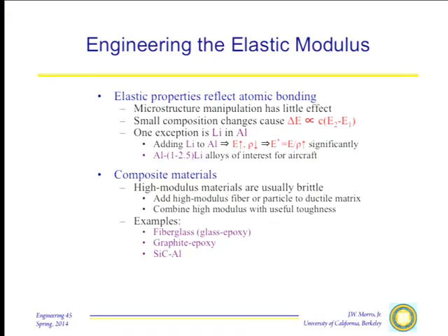You've got a problem because the limitations on the car will be the performance limitations, a good many of them, particularly dent resistance, go with the elastic modulus. That's the buckling behavior. So you can try shaving the body of the car down. I think I mentioned to you earlier, the first car I had had a 20 mil sheet bumper. No way you would dent that unless you ran into something pretty hard. These cars these days, you put your thumb in them, you can dent them if you want to. That's because they've shaved that metal off just as much as they possibly can. But you can't shave it too far or it would dent in the wind.